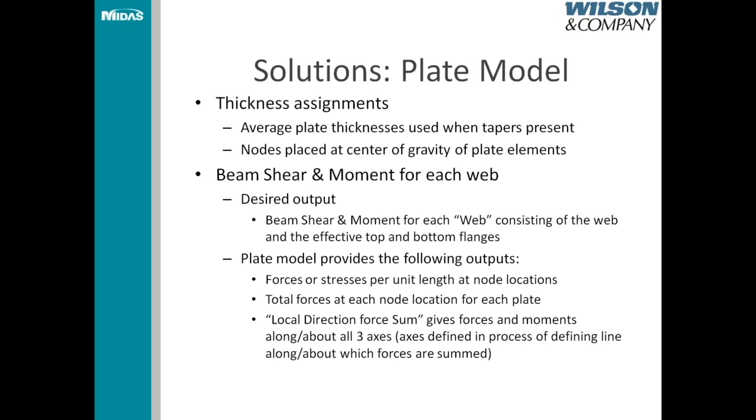The plate model provides the following outputs. We're looking at forces or stresses per unit length at each of the node locations, and the total force at each node location for each plate. There's also a tool called the local direction force sum. This gives forces and moments along or about 3 axes. The axes are defined in the process of defining the line along and about which the forces are summed.